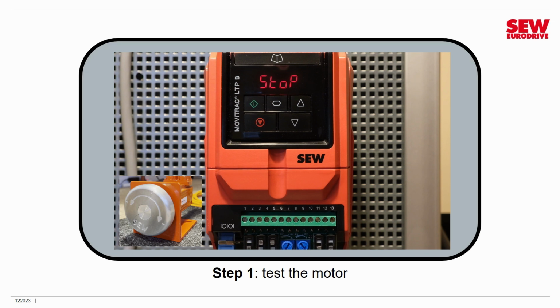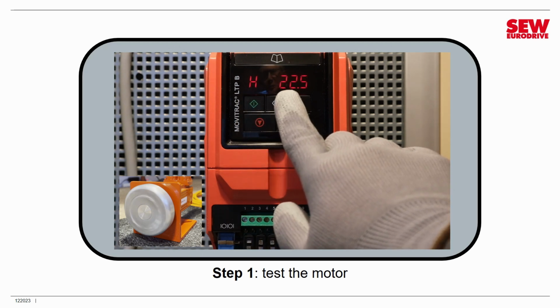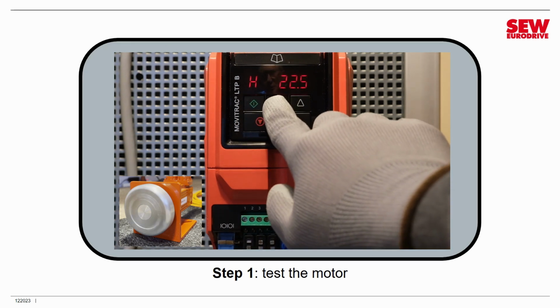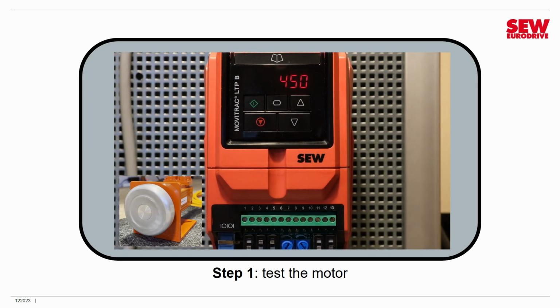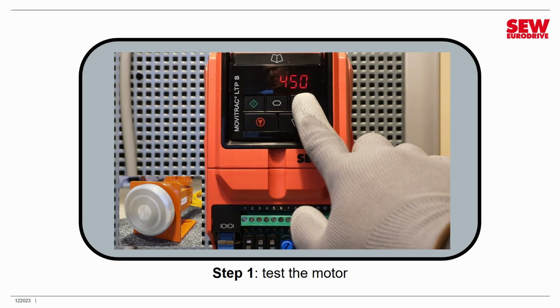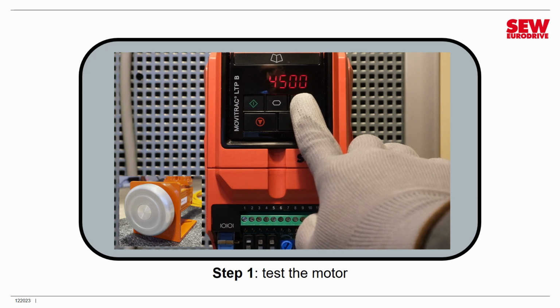So now I'm going to press the start button again, and this time it should run. It should go to the minimum speed, which is 450 RPM. We're on Hertz right now on our display, so I need to press navigate to get the RPM display. There we go. It's 450. Appears to be running fine. Let's accelerate it up all the way to 4,500 RPM just to make sure our motor runs smoothly up to its full speed range. And it seems just fine.